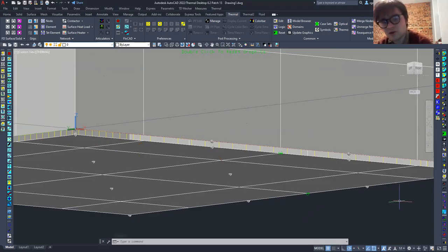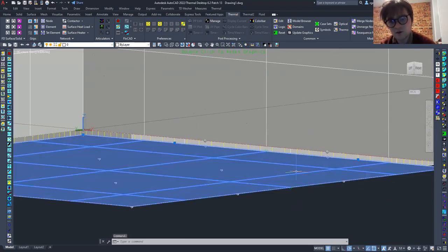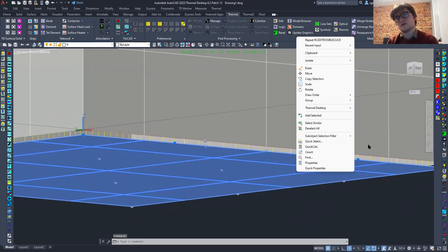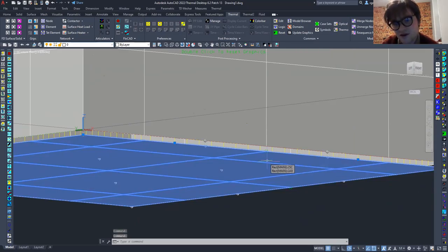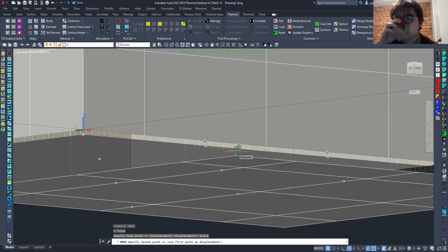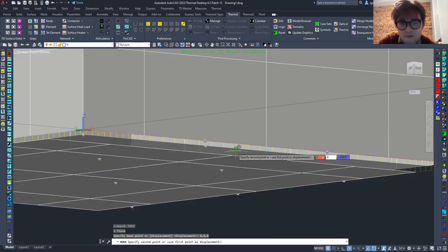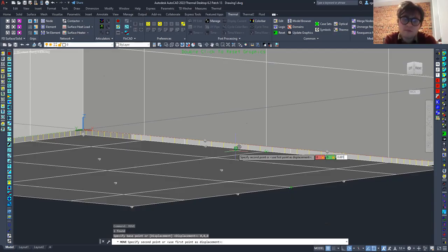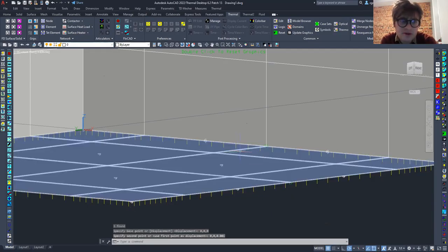So now you can move that back up a millimeter. Go ahead and click it and do the move command. This time I'll just click it and type move, and then put your base point at 0, 0, 0, and then your reference point that you want to move up to 0, 0. Instead of negative 1 millimeter, just do positive 1 millimeter. So now it's back in place.